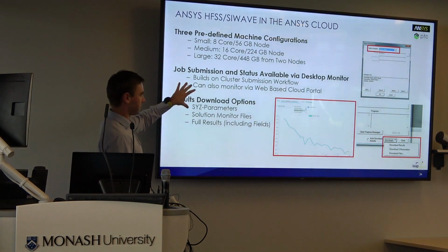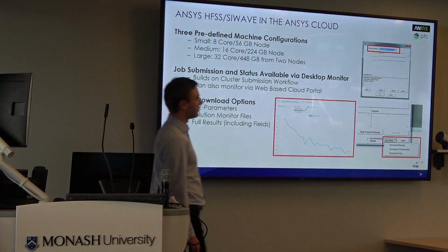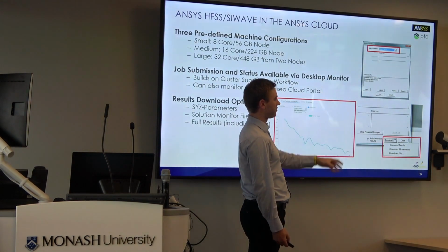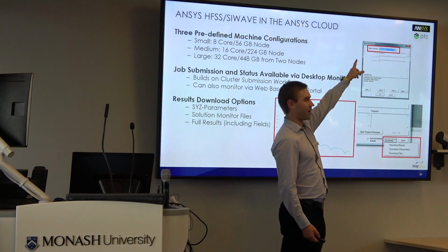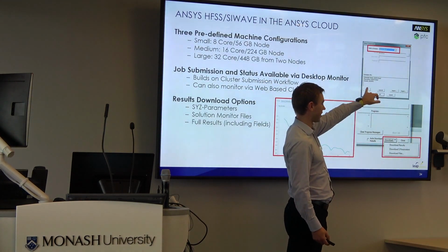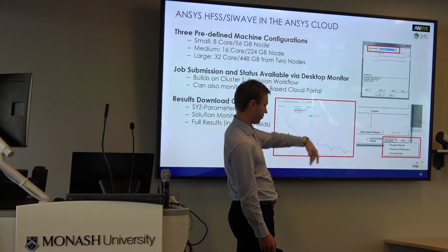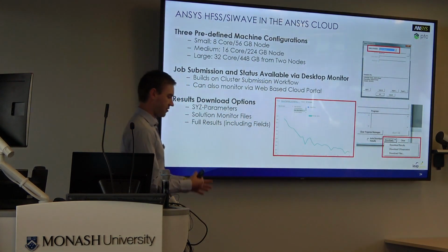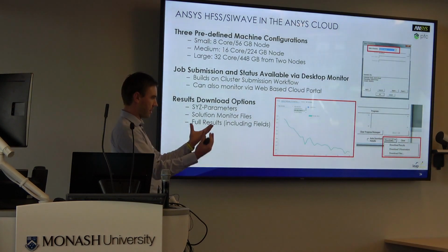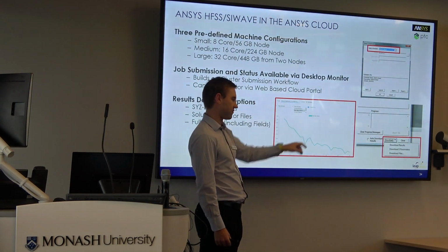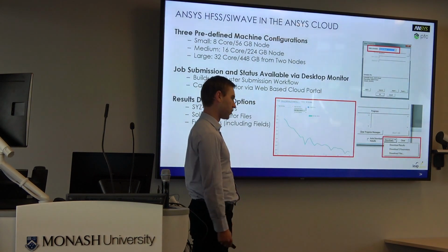Basically what happens is you set up your solve in Electromagnetics Desktop, you go to what used to be thought of as just the cluster scheduler tool, and you choose ANSYS Cloud instead of a cluster, and then you log in, and that gives you access to your elastic compute unit. Then you push launch, and it submits it to the queue, and then it solves automatically in the cloud. You can watch it converge and see all the normal post-processing stuff that you would get. You can do it on your phone if you're bored.